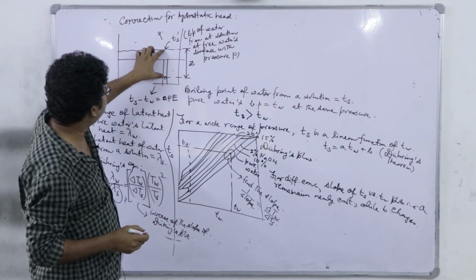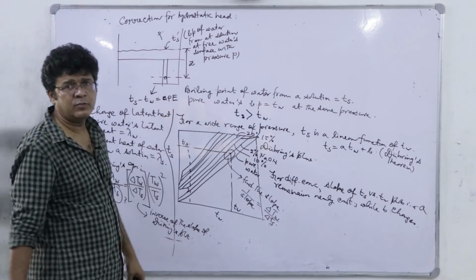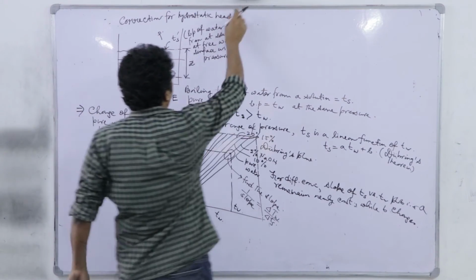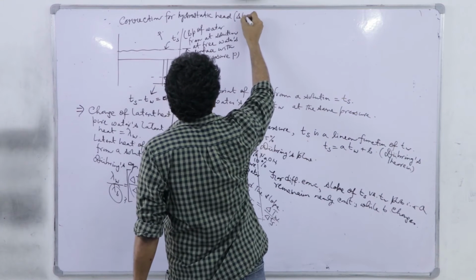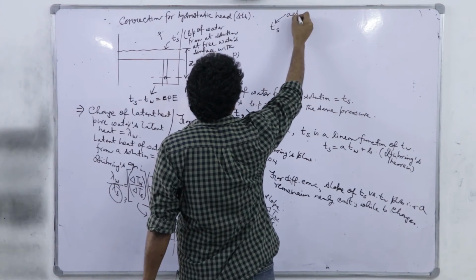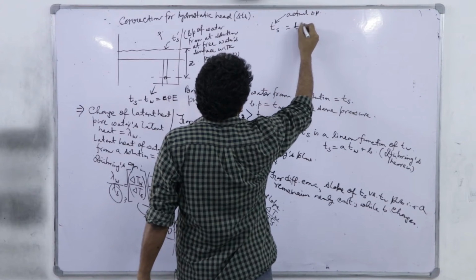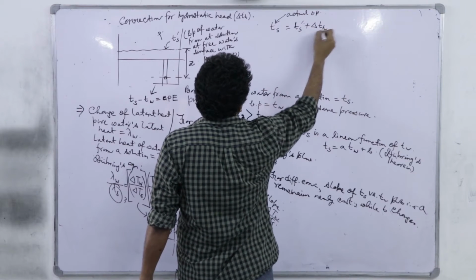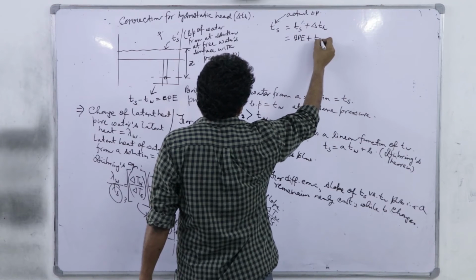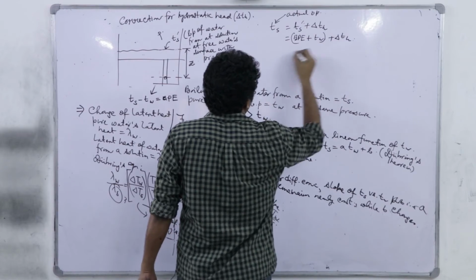Now additionally, because of this Z, there will be a change in boiling point, and that we refer to as the correction for hydrostatic head, delta Th, right. So the true, actual boiling point is Ts prime plus delta Th, which is alternatively the boiling point elevation plus Tw, that is Ts prime plus delta Th.